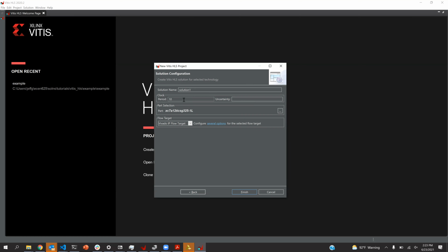So I'll refer back to 330, where we talk about how much work you can do in each state in your state machine in software before you miss interrupts. It's the same analogy in hardware. You can only do so much work between clock ticks. If you try and put too much combinational logic there, then you're going to violate the clock period.